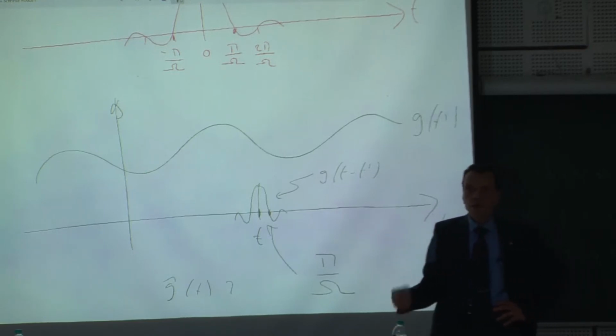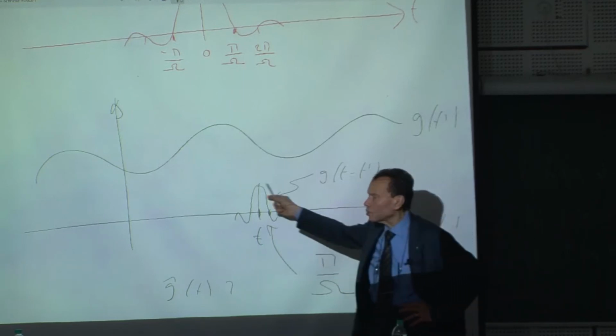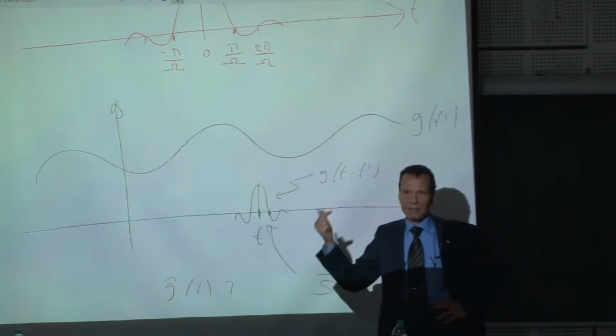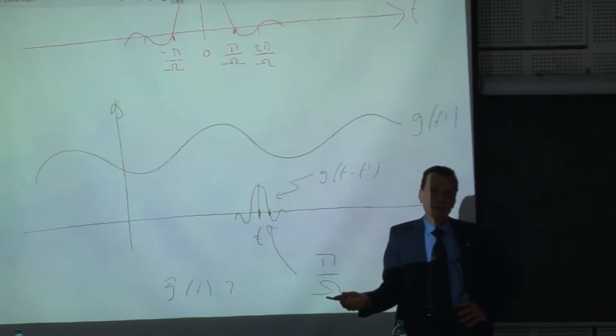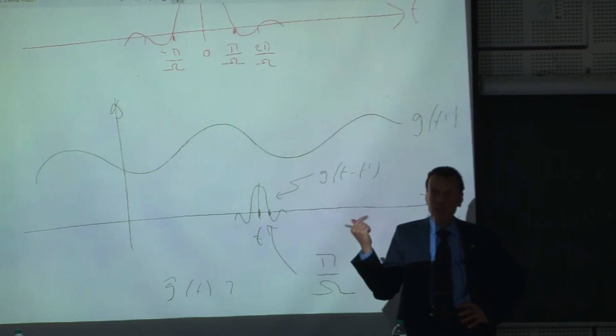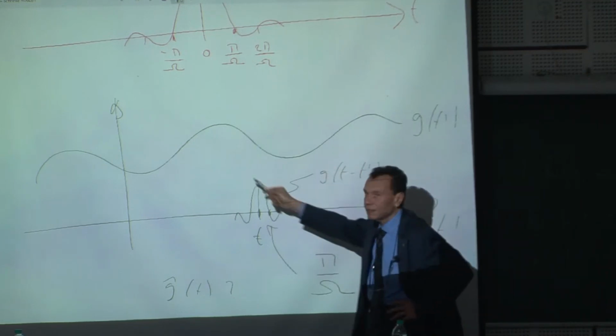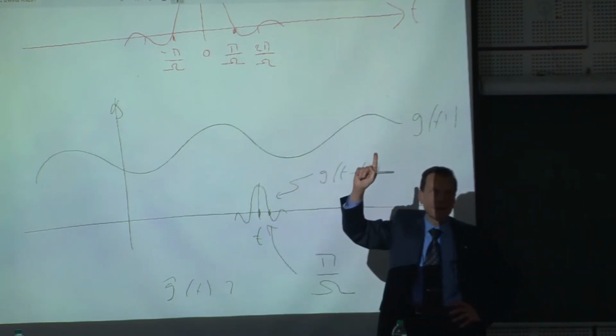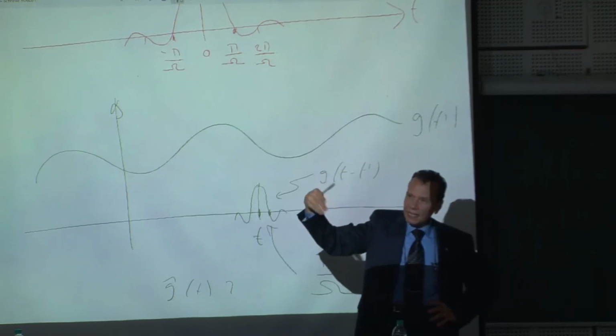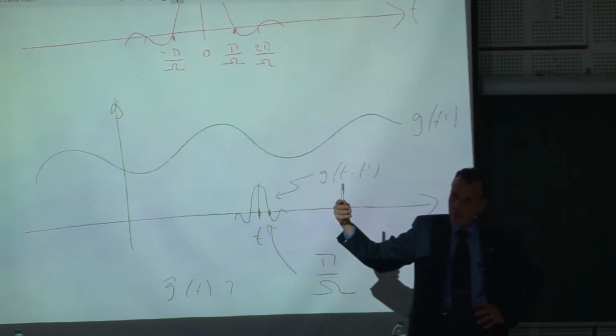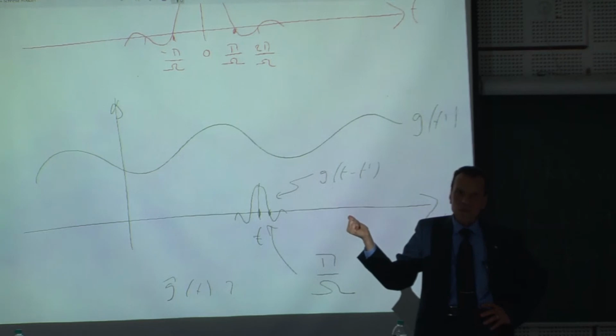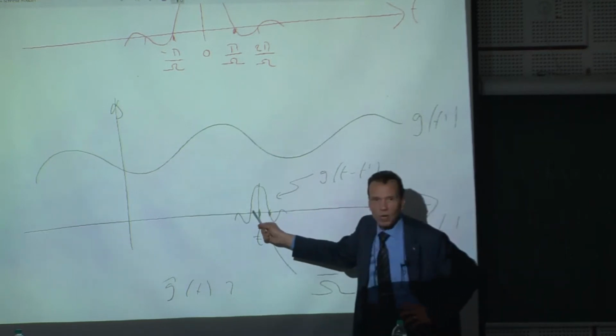In the imaging community, this thing here is called point spread function. Why is it point spread function? Because really, if you have a point source, if G is Dirac, and you try to retrieve this Dirac by the limited bandwidth measurements, you convolve this one with Dirac.